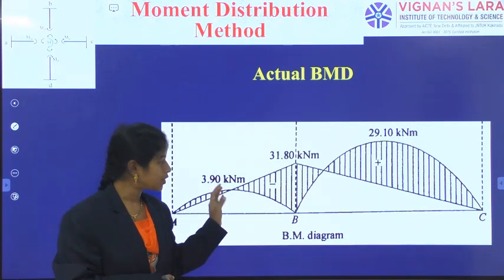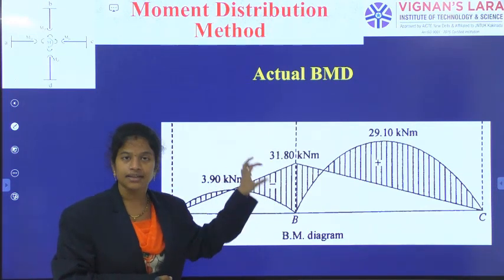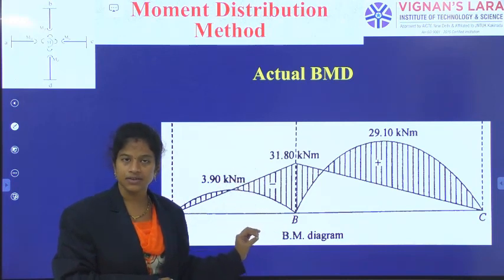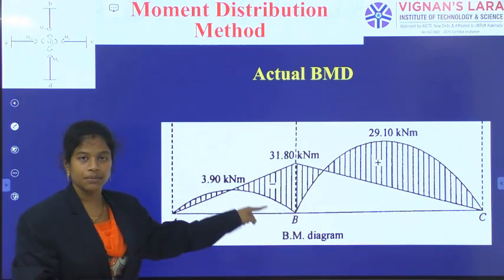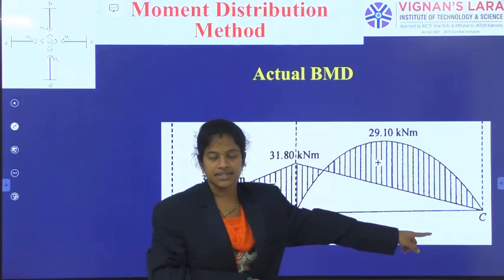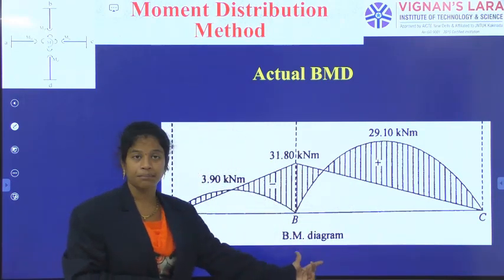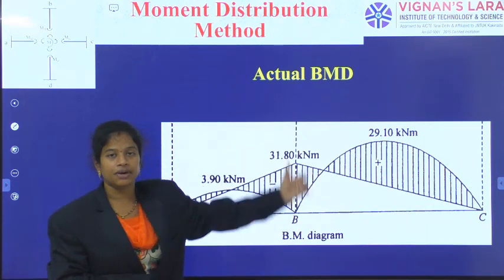the free bending moment diagram, you can generate the actual bending moment diagram like this. Okay, 0 hogging moment at B, 0, and then free BMD in AB, free BMD in BC. Merging those two, you have actually got the bending moment diagram, that is the actual bending moment diagram.